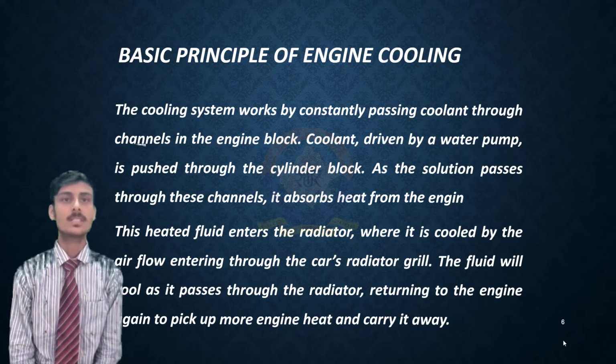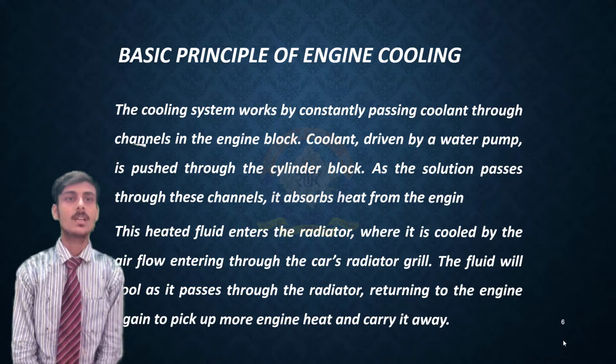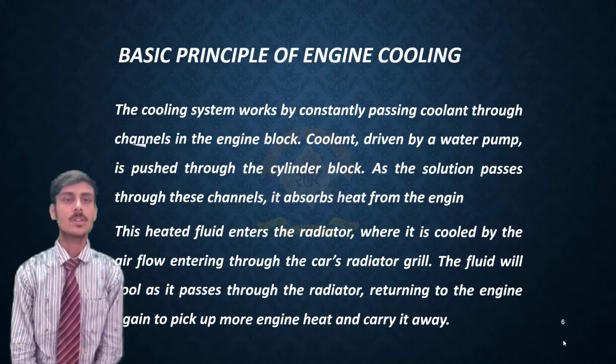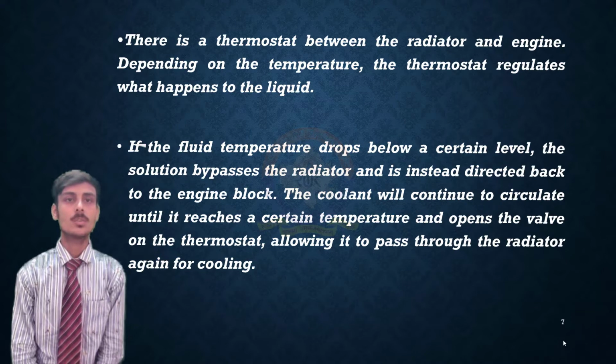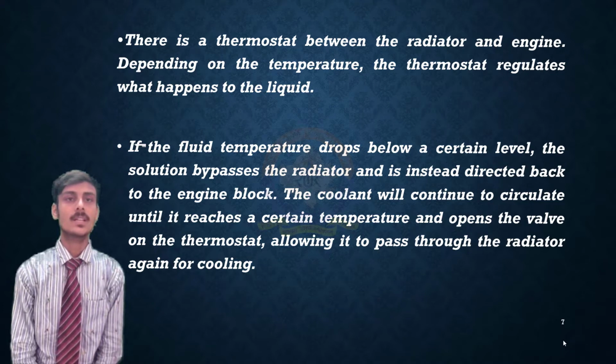Now let's understand the basic principle of engine cooling. The cooling system works by constantly passing coolant through channels in the engine block. Coolant driven by a water pump is pushed through the cylinder block. As the solution passes through these channels, it absorbs heat from the engine. This heated fluid enters the radiator, where it is cooled by the airflow entering through the car's radiator grill. The fluid cools as it passes through the radiator, returning to the engine again to pick up more engine heat and carry it away.